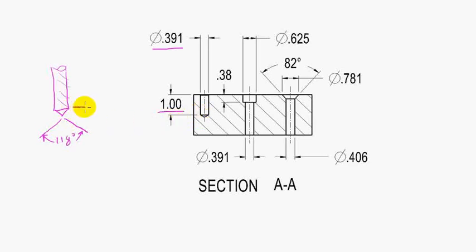So to right here, that's where the depth goes. The drill point is excess depth of the hole, and it's not a full hole beyond that depth. So in this case, if our two-place decimal had a tolerance of plus or minus 20 thousandths, this hole would have a full depth anywhere from 1.020 maximum to 0.980 minimum.